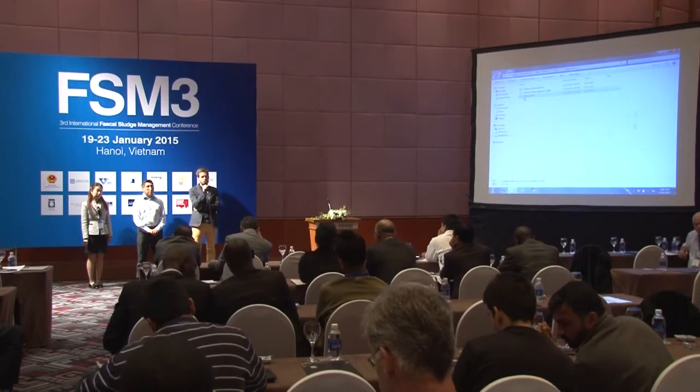So I would say it was fairly random how we picked these conditioners, and yes, they're not the right conditioners for fecal sludge. They are conditioners commonly used for mechanical dewatering. They produce really high flocs, so they're more resistant to decanting and centrifugation and these kinds of things.